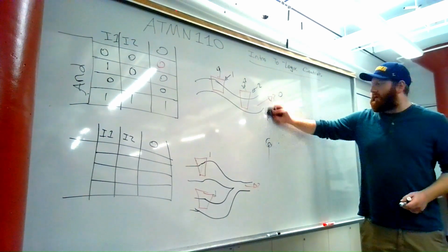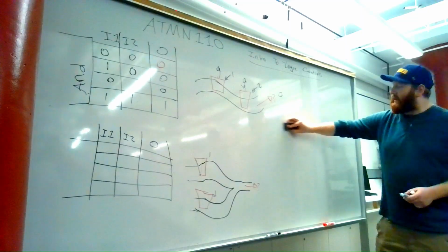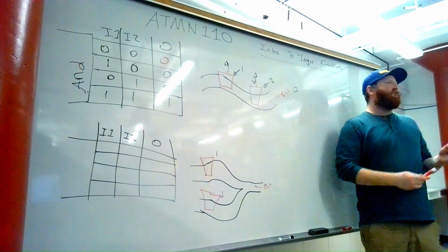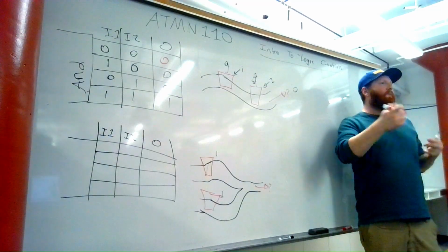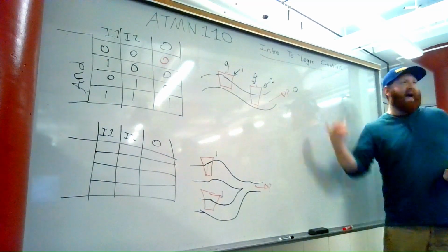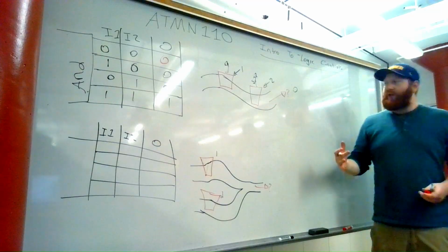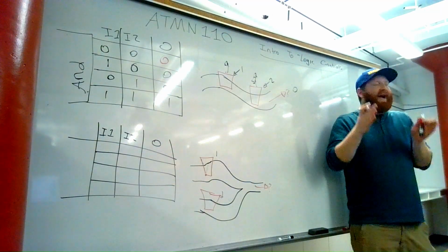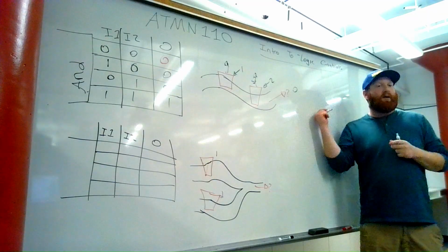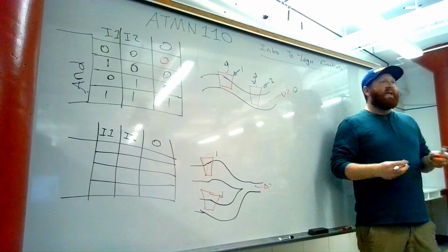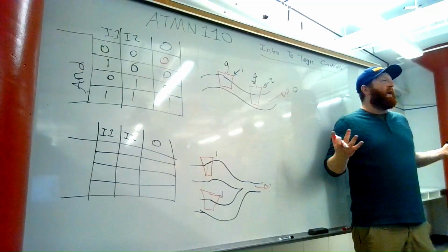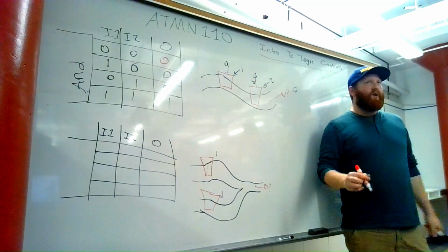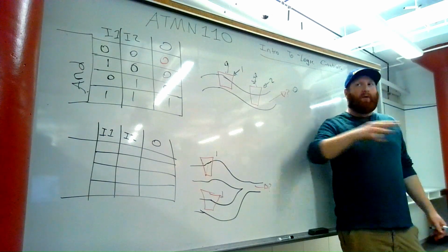Okay, let's get this. Now, here's a few good things for housekeeping in general. Whenever you're drawing or wiring from 24 volts, use red. Whenever you're going back to ground, use black. Whenever you have a schematic on your circuit, you want to lay things down exactly the way they are on the schematic on your table. It's going to make your life really easy to be able to build your circuits and get through everything you want to, okay? And also you want to keep in mind the flow of your current.